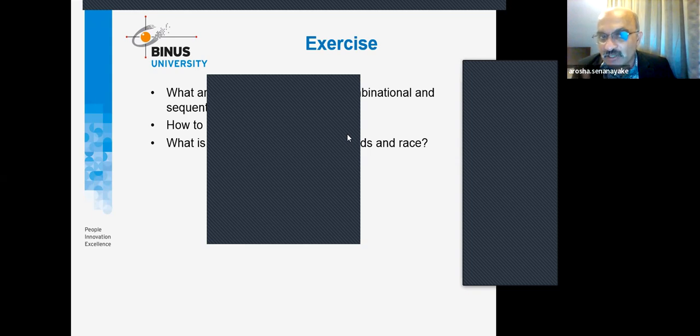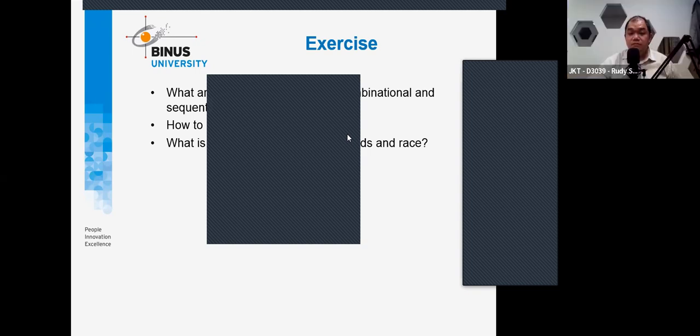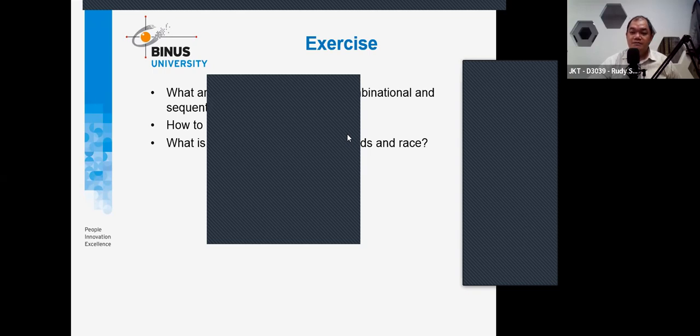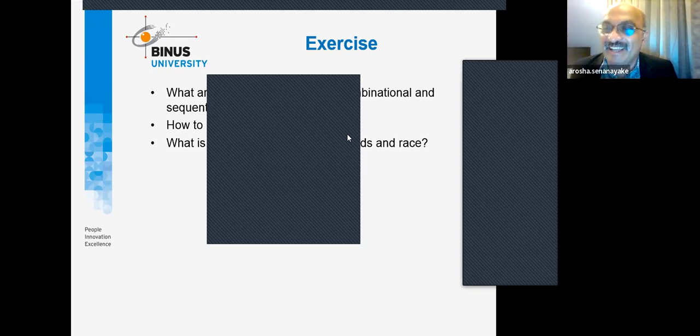Not only that, there are really two different types. If you have microprocessors or microcontrollers with a processor, it is usually CMOS. And then when it comes to gates, most of the time it is TTL. That itself is troublesome. People expect that there is no problem, but it is not the case. Actually, the delay is entirely different.